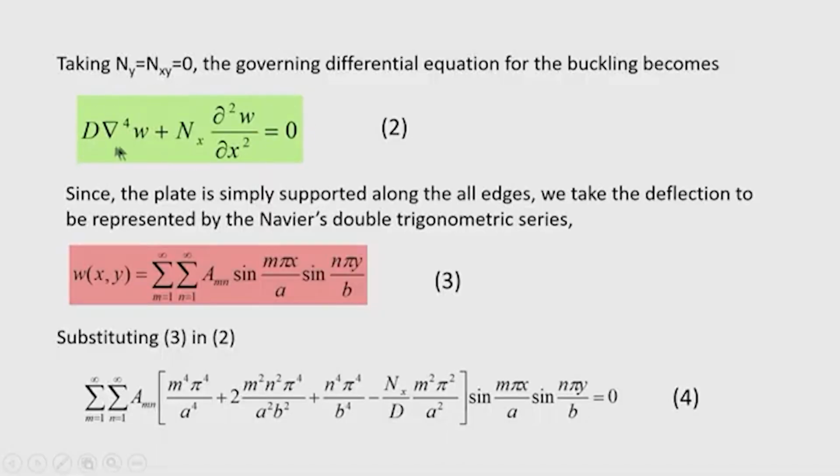So, we take it as a solution of the differential equation of the plate for the buckling. Now, you can note here, for buckling analysis we have not considered any transverse load, because this is a homogeneous solution of the differential equation that will yield the buckling loads. After imposing the boundary conditions, the characteristic equation that forms is a homogeneous type of equation, and in most cases you will find the equation is formed in the form of trigonometrical or hyperbolic functions.